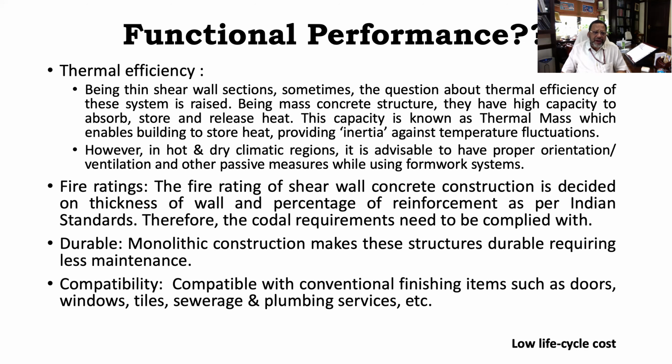The second question comes about fire rating, because the walls are thin. A 100 mm wall may not stand the fire rating for residential structures. So here we need to comply with the codal requirements in letter and spirit. Whenever we do this kind of construction, depending upon the use of the building and depending upon the thickness and reinforcement, the fire ratings are given in IS 456. So those fire ratings need to be complied with.